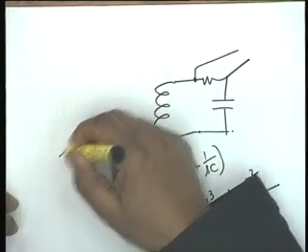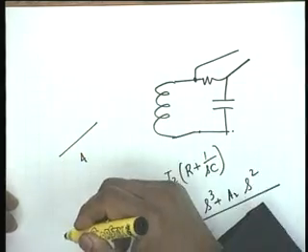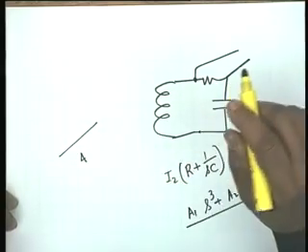Because the number of poles here is 4. You cannot create more than 3 zeros, and therefore there is no way that you can get a high pass response. You cannot get a low pass response either. There is no way that you can reduce the numerator to a constant, and therefore it is truly a band pass case.